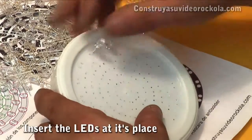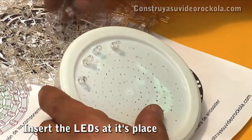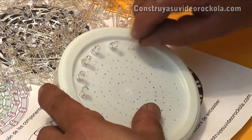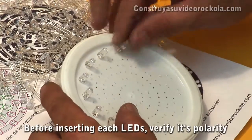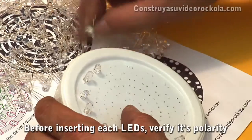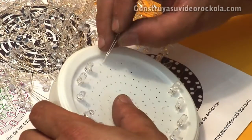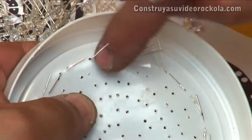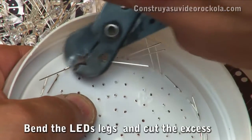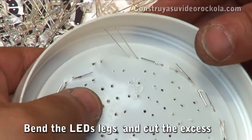Let's place them starting at the top, considering that all the LEDs stay with their negative pole facing the left side. In other words, the opposite of clockwise. To identify the polarity of the LED, we know that the short leg is negative. If by mistake an LED is placed upside down, the circuit will not start. We bend the legs of the LEDs and cut them to sufficient size so that the positive leg of each LED is followed immediately by the negative leg of the next.